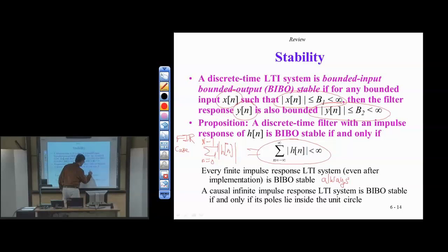If I think about it, there are only 3 transform pairs to really use in a class on a regular basis. The rest we look up. One of those transform pairs is an exponential sequence. And what is the Z transform for that? One over 1 minus a Z inverse. Very good. Z to the minus 1. And what's the region of convergence for this?